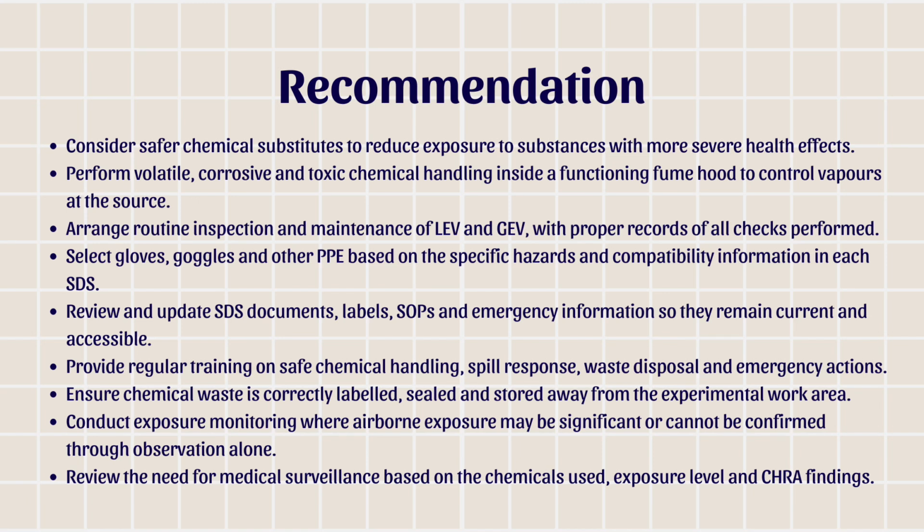Activities involving volatile, corrosive, or toxic chemicals should be performed inside a functioning chemical fume hood. This is important because vapors should be controlled at their source rather than relying only on general room ventilation. The LEV and GEV systems should undergo routine inspection, testing, and maintenance. Proper records should also be retained as evidence that the systems continue to function effectively.